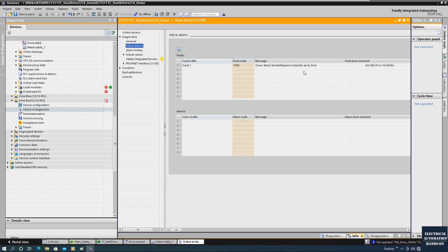However, while we're applying this torque reduction, actually this fault will cause trouble, right? If you try to stop the motor, which is totally fine, you can use this torque range and stop the motor once the torque reaches this limit. However, in most cases, we do not like this because we like the motor to keep running. Maybe if you apply a higher workload on this motor, the motor just jams here. It doesn't want to go, but the motor should not show the alarm. So how can we solve this?